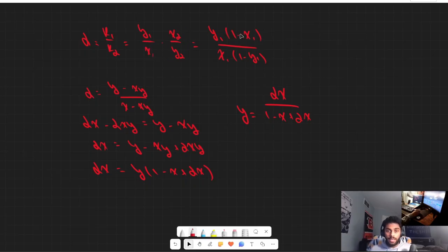We simplify it down to get everything in terms of one component. And from there, we go down and we get y alone, and we get a relationship that looks something like this. So this is going to be crucial in helping us get that XY diagram for our McCabe-Thiele plot.